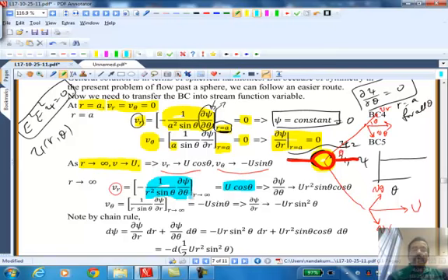And so I simplify this. I move the d psi d theta to the left side, everything else to the right hand side. So what I'm saying here is d psi d theta must approach, asymptotically must approach u r squared sine theta cos theta. The cos theta is here, the sine theta comes from the denominator, and the r squared also comes from the denominator. So the derivative of psi with respect to theta must approach this functional form, u r squared sine theta cos theta.